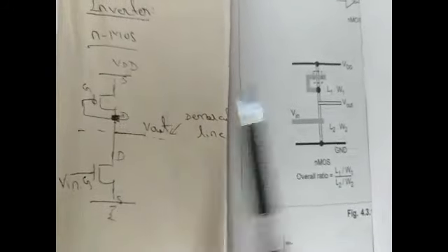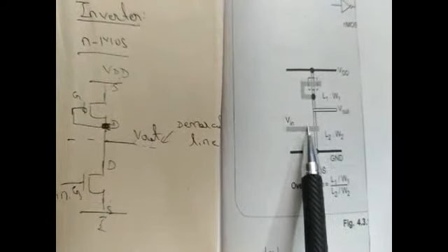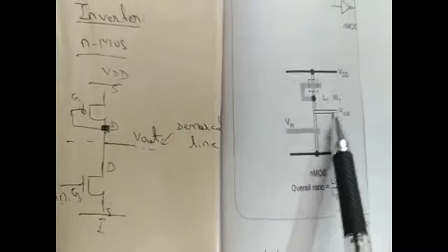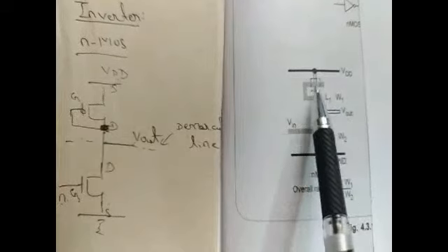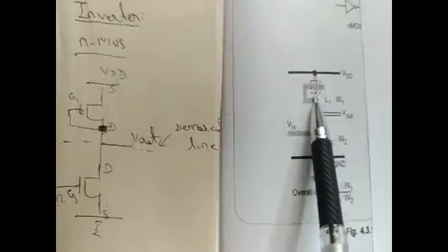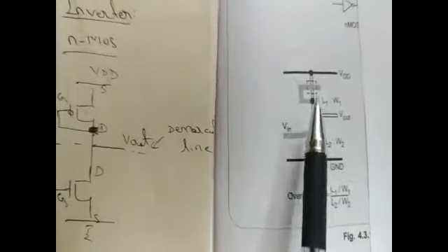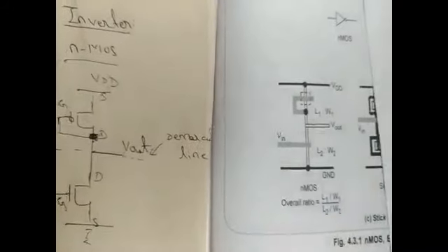Okay, and so here, what you are representing with the dotted lines is known as your polysilicon, which is acting as your gate region, and the dark lines are known as your VDD as well as the ground. Next, without any marking, it is known as your diffusion part, that is your FET. And this part with the dotted line is known as your N well region or the implant region.